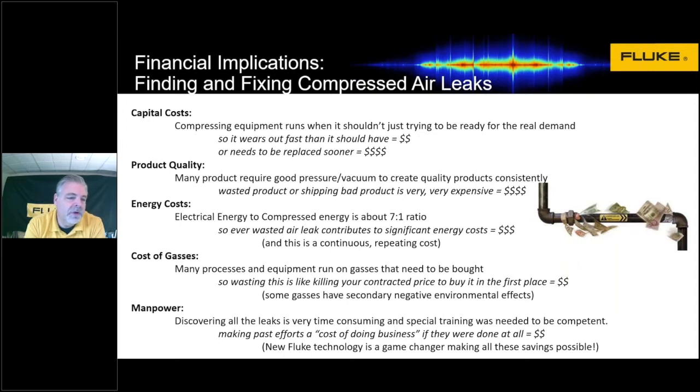From a product quality point of view, if you're making product that depends on good air pressure, having a leak or not having enough volume of air available to you because your compressors are leaking and not getting the air to your tools might result in lost productivity, bad product, and it can be very, very expensive if you have to find ways, especially if you're considering adding another compressor just to keep up to your load.